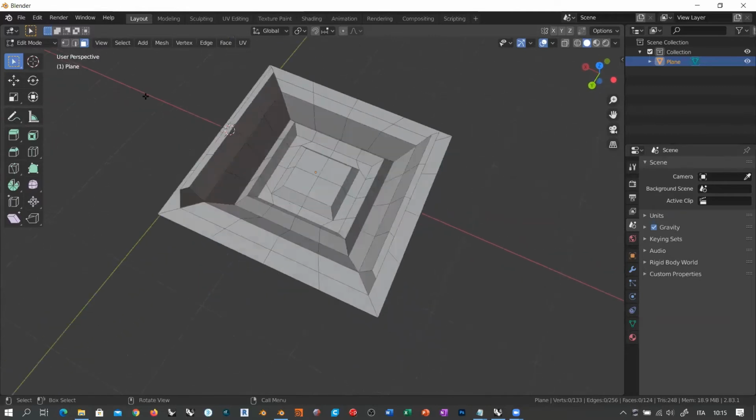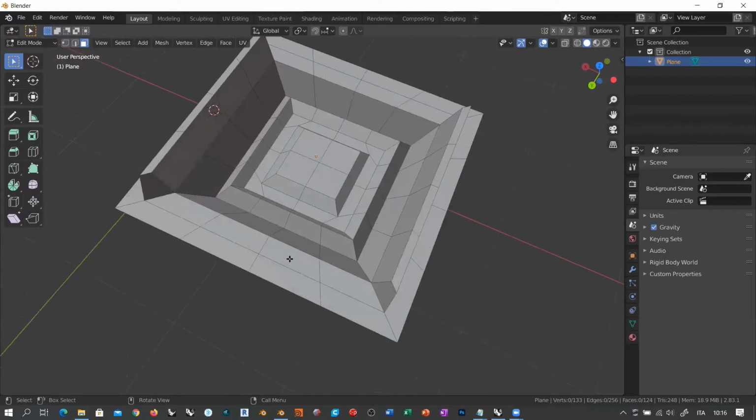There is a way when you are in edit mode and the face select tool, and you have this kind of complex object. If you click on one quad, you see that you only select one face. Let's say I want to select the whole U or V stripe of polygons at once.